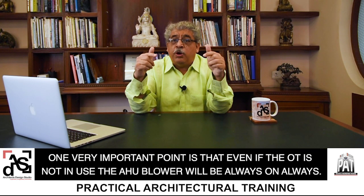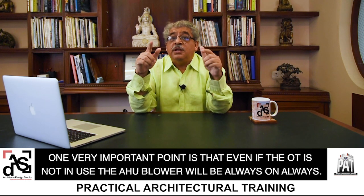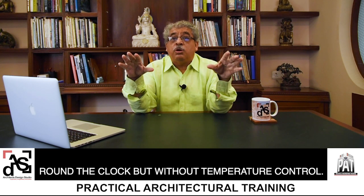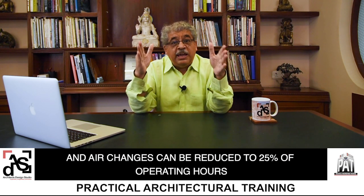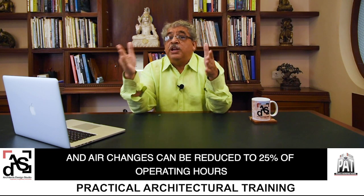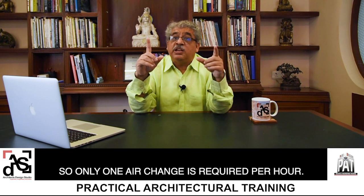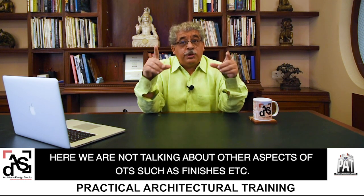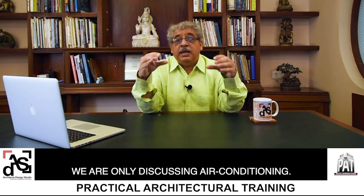One very important point is that even if the OT is not in use, the AHU blower will always be on, round the clock, but without the temperature control. And air changes can be reduced to 25% of operating hours. So only one air change is required per hour. Here we are not talking about other aspects of OTs such as finishes, etc. We are only discussing air conditioning.